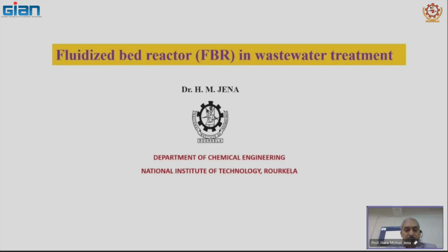At minimum fluidization velocity, the pressure drop across the bed equals the weight of particles and the bed becomes completely suspended. This is the general definition of the fluidized bed and the minimum fluidization velocity, beyond which the fluidization takes place. In a three-phase system, there are two different fluids. One is gaseous fluid and another is liquid fluid. The flow of these fluids may be co-current in the upward direction.